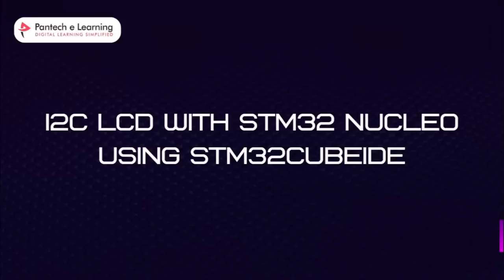This is where I2C comes in. I2C is a communication protocol that allows multiple devices to communicate with each other using just two wires, a clock line and a data line. I2C is a popular choice for interfacing LCD modules with microcontrollers because it requires only two pins, simplifying the wiring and reducing the number of GPIO pins needed.